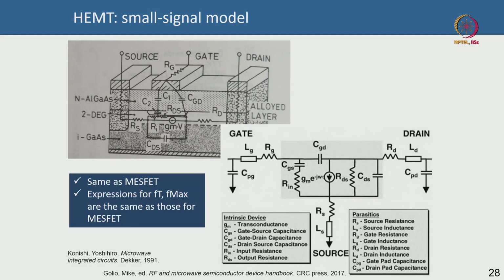Okay. So over to the whiteboard here, what I am showing you is a small signal diagram of such a HEMT. Again the same discussion on distributed versus lumped holds true as we discussed in our MESFET, but more importantly the small signal model of a HEMT is almost identical to that of a gallium arsenide MESFET. There is no difference here. The expressions for cutoff frequencies are also identical. There is no difference here, so we should not spend much time here, but I will again emphasize